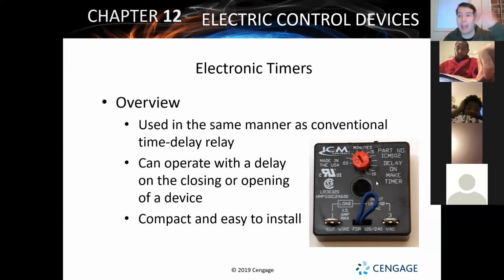These can be installed aftermarket as well. They don't have to be installed by the manufacturer. You can put a time delay relay like these ones here on just about any compressor motor or any system you see out there nowadays, because it's a good safety to have. It's going to prevent short cycling from occurring, and when short cycling occurs, it's going to really burn out a motor and hurt most of our components.